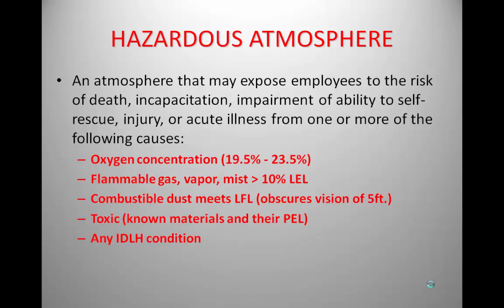Combustible dust meets LFL, lower flammable limit, and the lower flammable limit is the point which will support combustion. A general rule of knowing if you're in a combustible dust environment is if it obscures your vision more than 5 feet, you can consider that as a flammable atmosphere and dust. Now keep in mind that's a general rule.